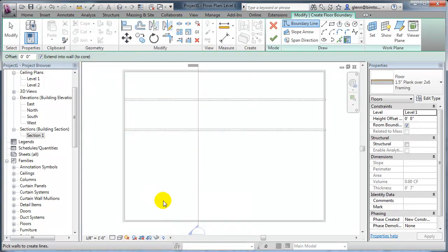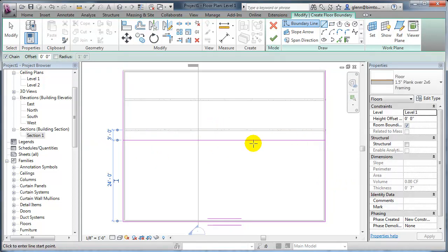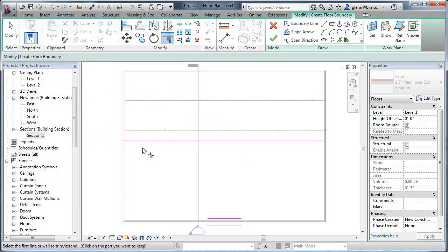So what I am going to do is put it over part of the building. I will say that we're going to choose some walls. Pick those. Let me go through, and what do I want? Because I'm going to use the foundation walls as the boundary. For the level, this is where we get to think about where the top of the subfloor will be, and it will be right at level 1, so that height is actually looking good. Let me pick this wall. I'll pick this wall, and on the back side, just so I can put 2 different systems in here, I'm going to close it off with more of a line back there, and we'll join it from the other side. Let me trim this floor.